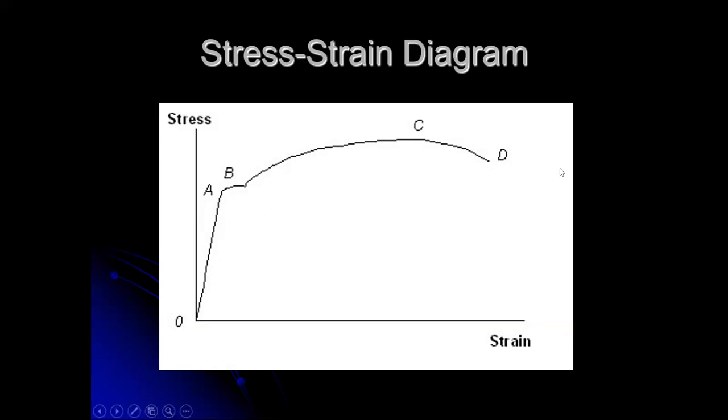Now, this is typical of steel. Aluminum tends to behave similarly for the proportional side. The slope of the proportionality, by the way, is Young's modulus. The slope of this line essentially tells us the relationship between stress and strain. That's Young's modulus. The bigger Young's modulus is, the steeper the slope. It's the ratio of stress to strain.